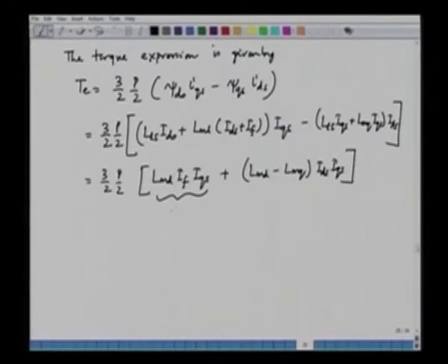And the first component here is the synchronous machine torque. So, we can say this is the reaction torque or the synchronous machine torque or the field torque. This is better termed as the field torque. This is because of the field winding current. If the field winding current is equal to 0, this component of torque will vanish. And the second term is called the reluctance torque. This torque comes into picture when there is a difference of inductance between the D and Q axis.